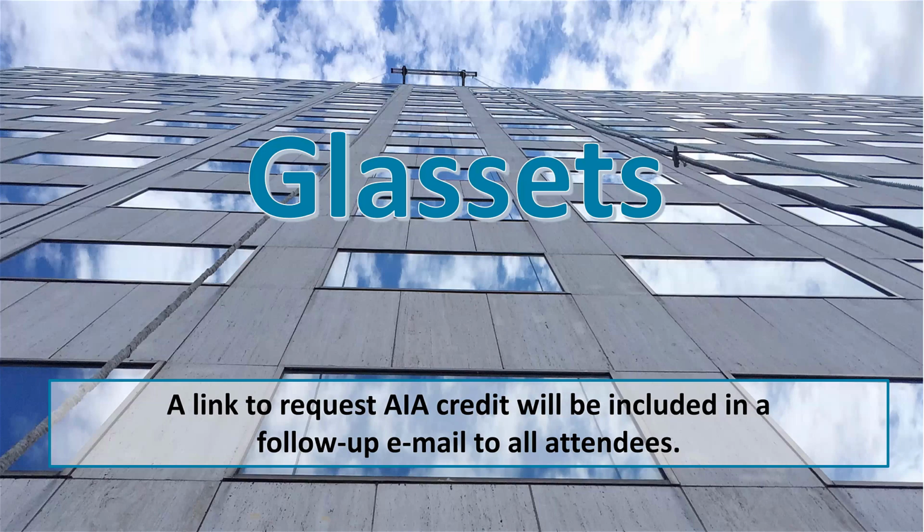Stephen, did you want to add anything to that? No, I think Mark covered it well. And so the short answer is we expect heat strengthened glass to break more like annealed glass versus the small dicing, if you will, effect that we get with fully tempered glass.